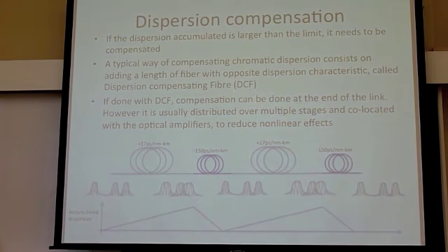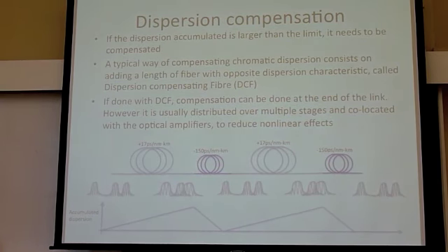By doing what's called direct detection, you lose all the information of the phase, what happens to the phase. Okay. So in theory, dispersion basically just means if I have a transfer function h, at the end I just put something which has a transfer function of 1 over h, and that's totally compensated. But the 1 over h is not just made on the power of the signal, but also influences the phase.